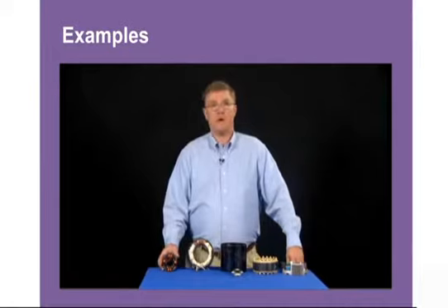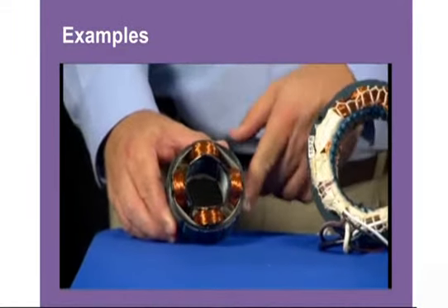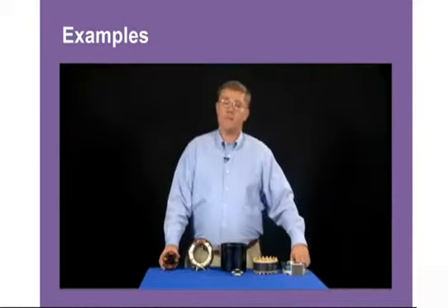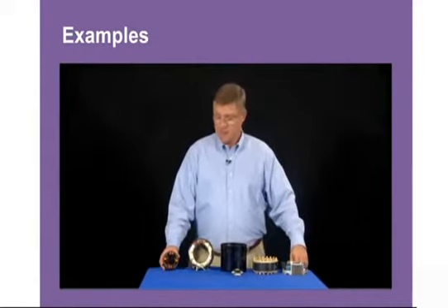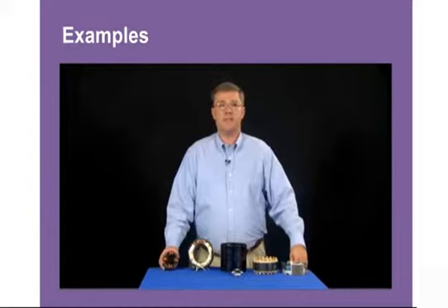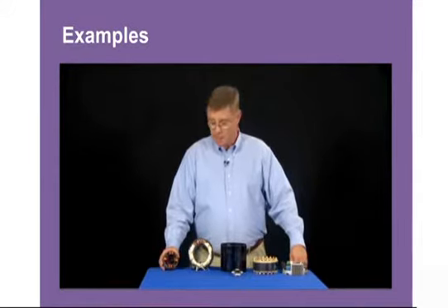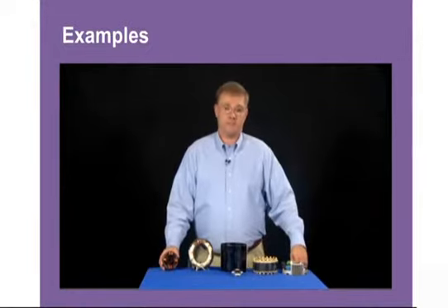This motor has one distinct coil or run winding, and there are shading bands or copper bands that are forced through the stator that help fix the rotation of this stator. This is the least efficient motor there is in the HVACR market. A shaded pole motor is between 30 and 35% efficient.